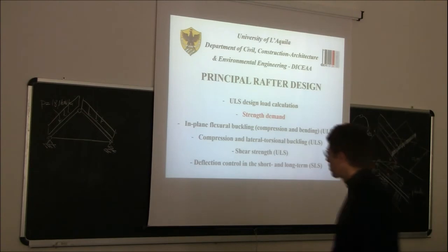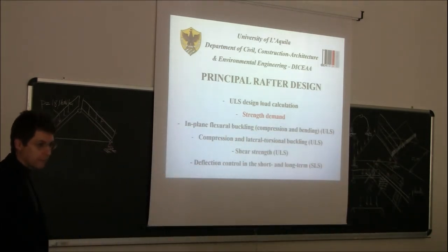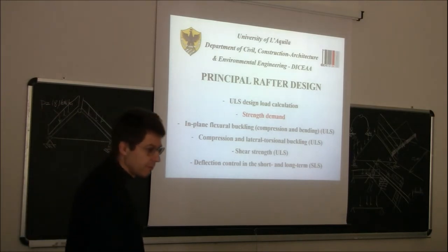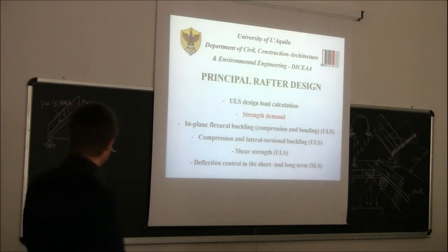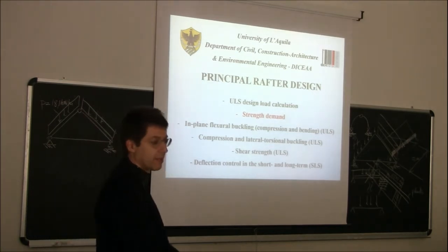The degrees of freedom: we should write the degrees of freedom of the 1, 2, 3 bars, and the restraints. So the number of degrees of freedom of those 3 bars, which are rigid, is 9 in the plane.